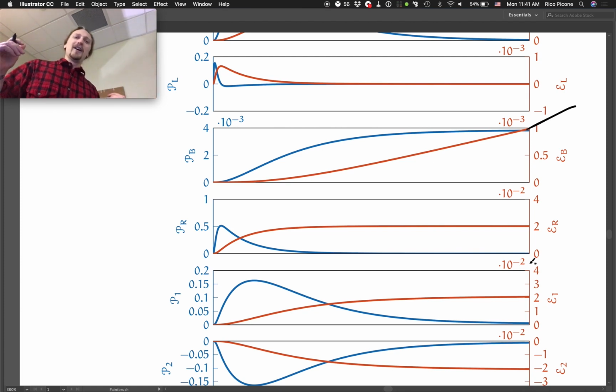If you have a motor that has very little damping, like magnetic levitation in a vacuum chamber, you get that thing going, and no current needs to flow unless you have any dissipation. And if you have any dissipation, like rusty bearings, then you're going to have to flow a lot of current just to turn the thing at a constant speed. So there's that. All right.